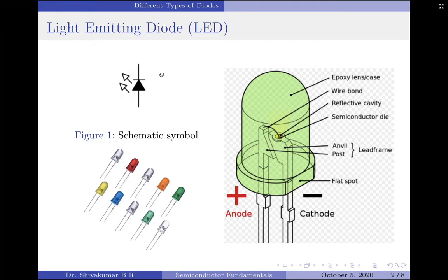The basic idea behind its operation is fairly simple. In a forward biased PN junction, when free electrons recombine and fall into lower energy valence holes, they must give up this energy differential in some manner. In most diodes, this energy is emitted as heat. In LEDs, however, the energy transition is designed such that it is radiated at shorter wavelengths, that is, visible light.